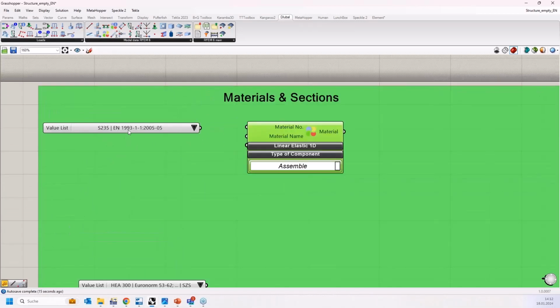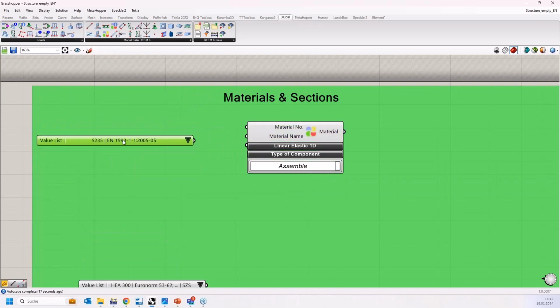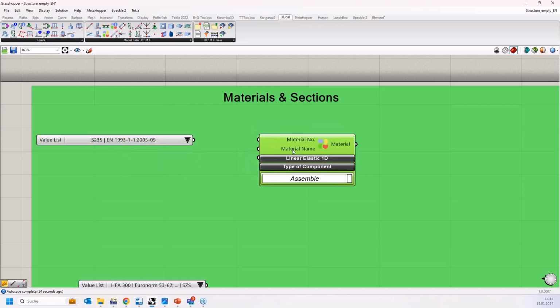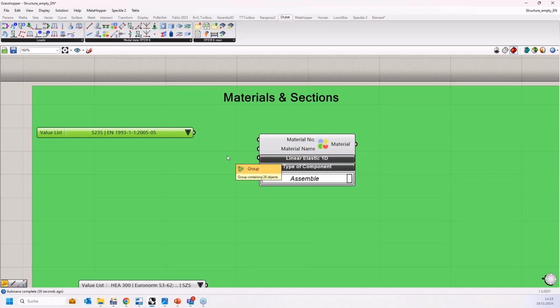I want to define a simple material based on our library. Yeah, in RFEM, we have a material library. And if you define the name here according to the name in our library, then it will create this material based on the library. Now, how can you define a name? The name definition is quite easy. You can use a panel, and inside that panel, you write the name.